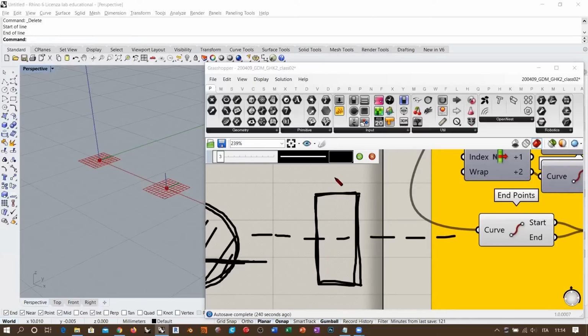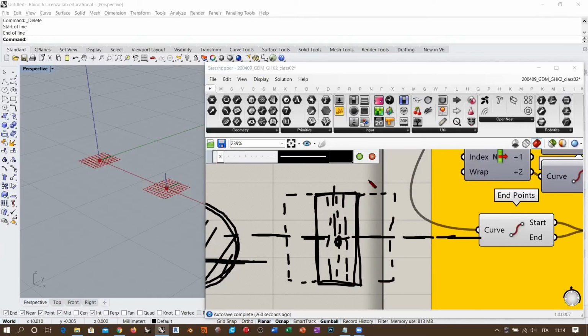What it takes into account is that with respect to this central axis, the longitudinal axis of the beam, this object could expand and therefore become longer, or it can contract. This is what the Young modulus affects. Then there is the shear, which is an expression of the possibility for this chunk of material to do something like this. This is the graphical definition of shear.